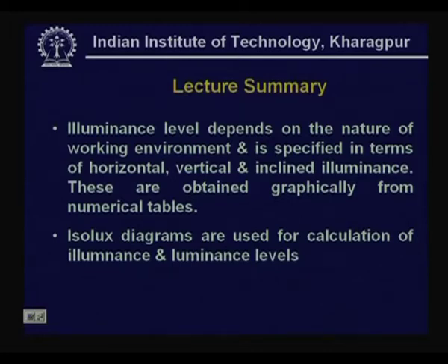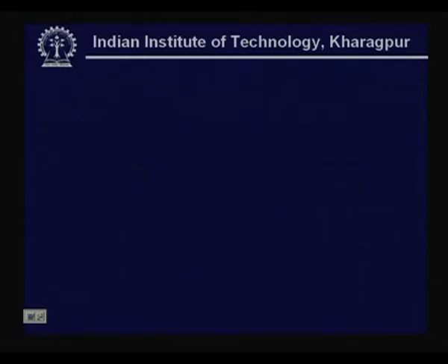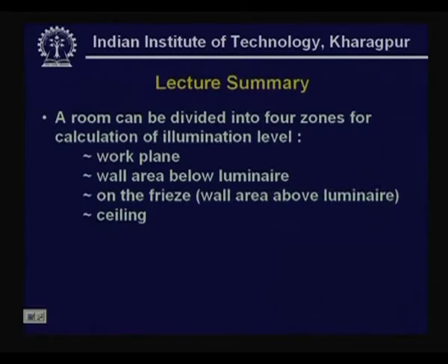The isolux diagrams together with polar diagrams for the luminaires are used for assessing illuminance levels in calculation. Depending on the nature of the service, one has to work out both on the horizontal as well as the vertical plane.